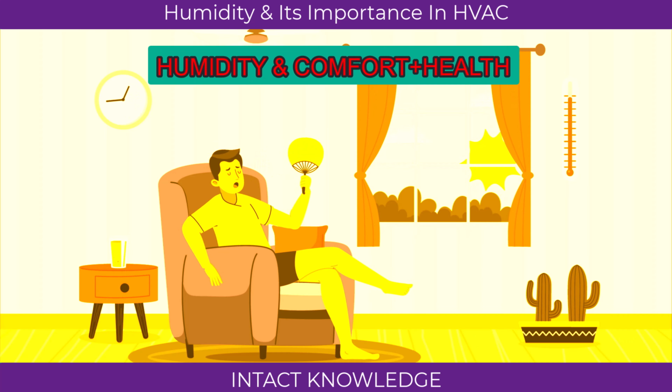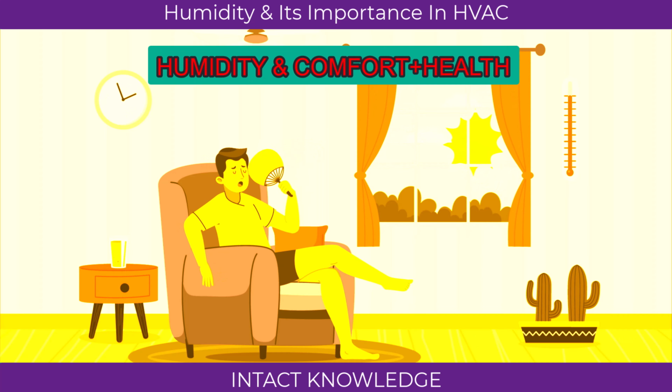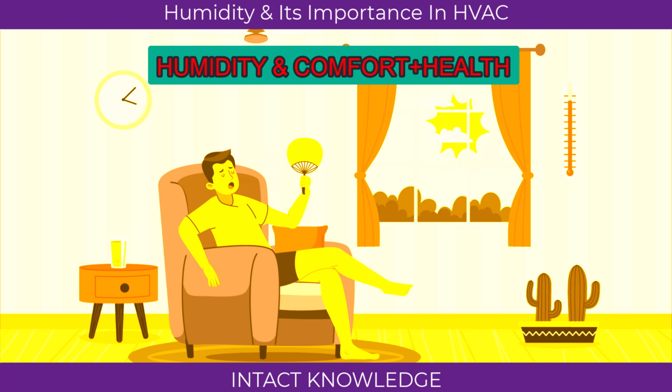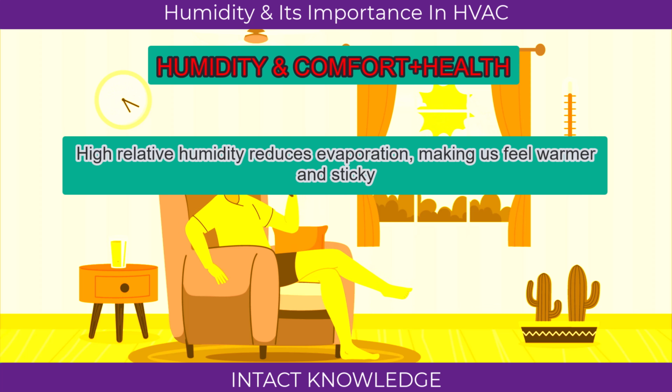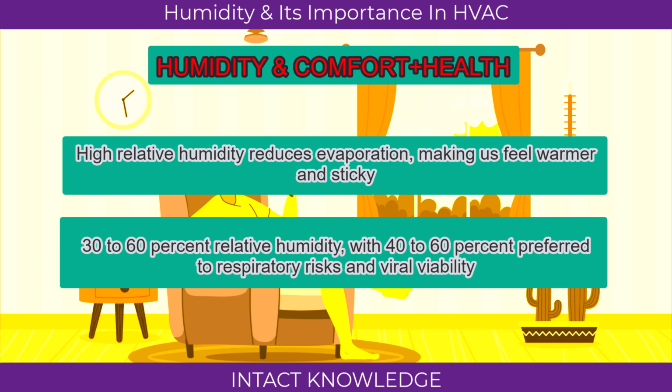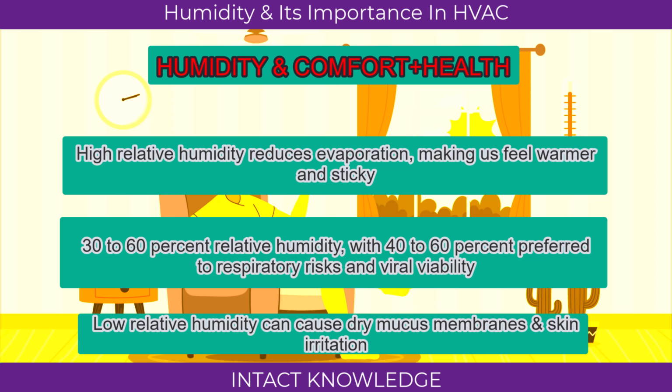Effects of humidity on comfort and health. Our bodies rely on sweat evaporation to cool down. High relative humidity reduces evaporation, making us feel warmer and sticky. Guidelines recommend 30 to 60% relative humidity, with 40 to 60% preferred to reduce respiratory risks and viral viability. Low relative humidity can cause dry mucous membranes and skin irritation. Rule of thumb: keep indoor relative humidity below 60% for health and building protection.